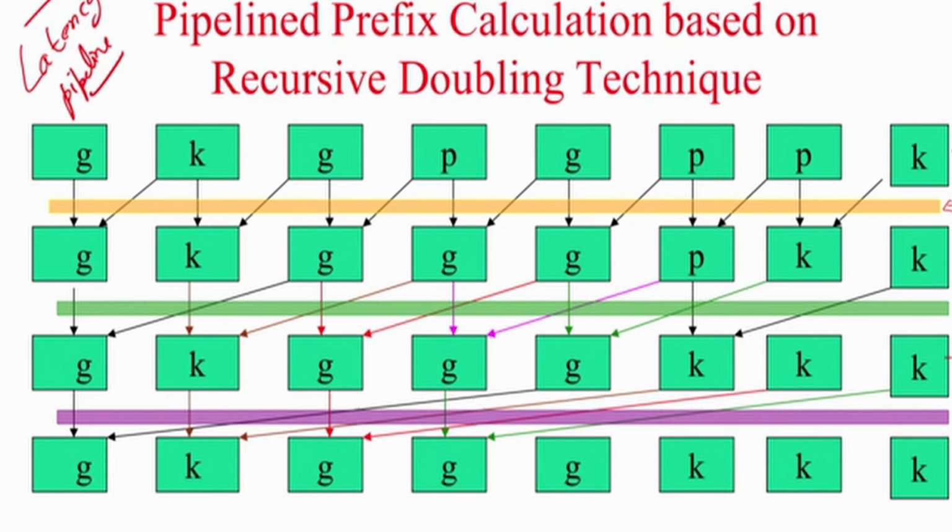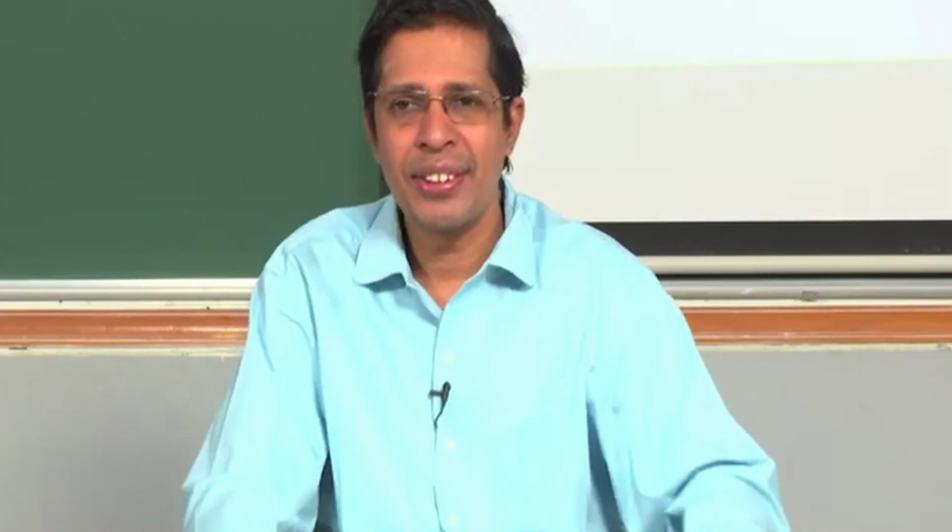So, when a data enters, all the 4 levels do some computation, and when the level k is performing the computation, all the remaining 3 levels keep quiet or they do not do anything sensible there. Either they are maintaining the value or they are just idle. So, that is something we have exploited to get this pipeline behavior. Fair enough? Did you follow?